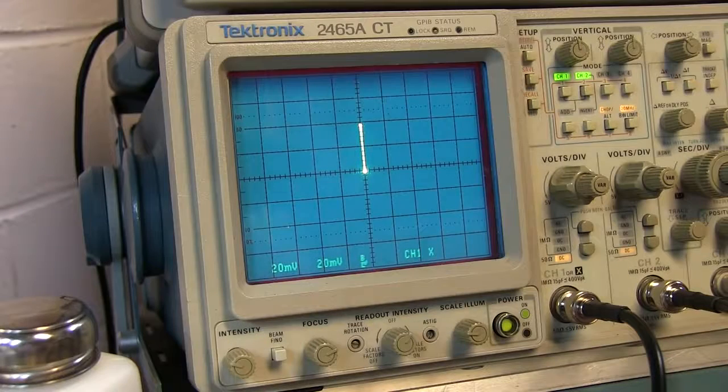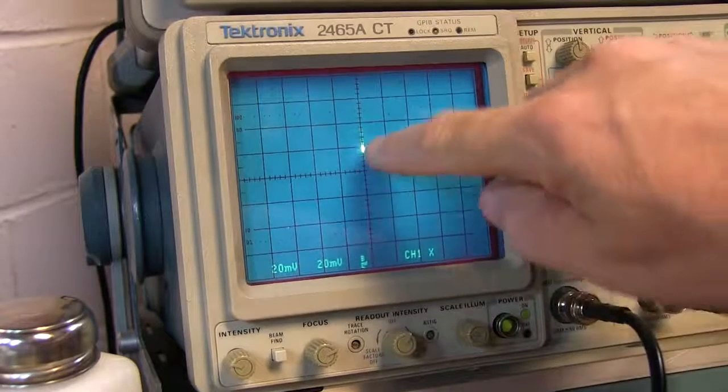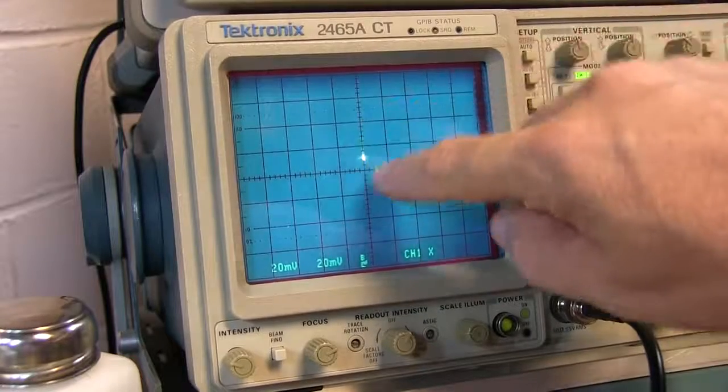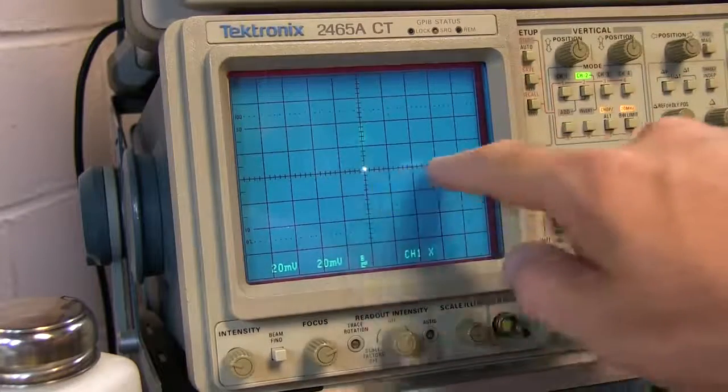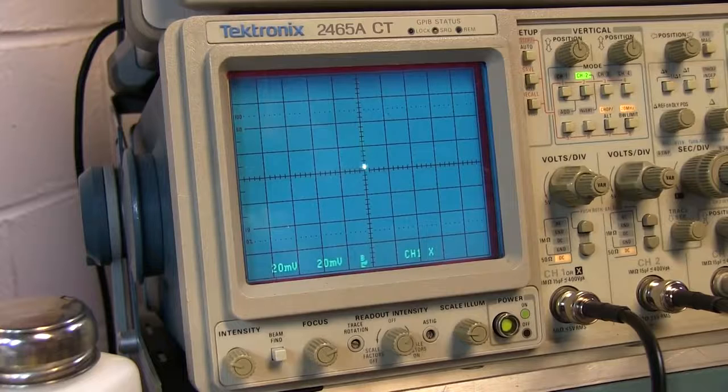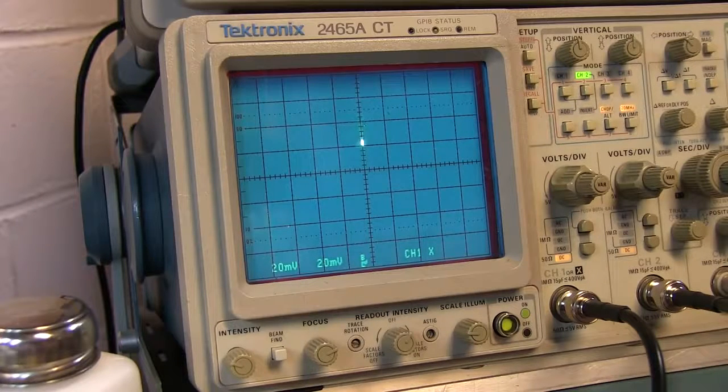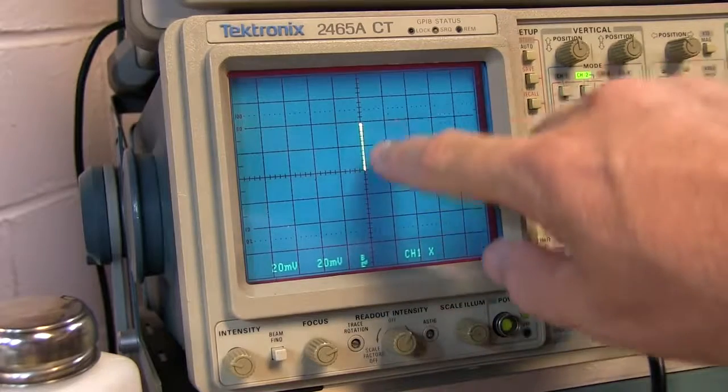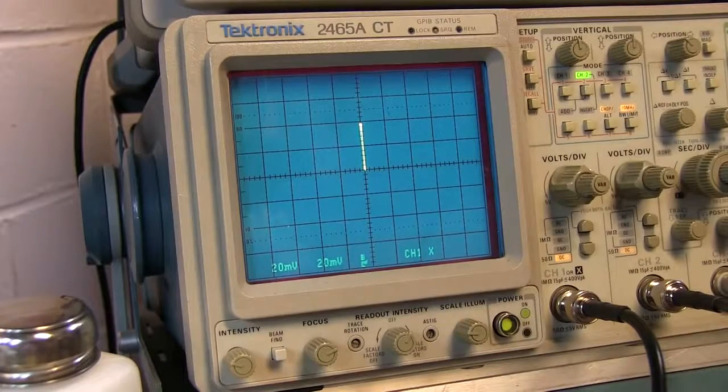If I slow the amplitude modulation baseband frequency down, let's bring it down to say 1 Hertz, now you can actually see the amplitude of just that Q component varying, with the I component being 0. Now for the purposes of visualizing that vector or that phasor, let's keep the baseband frequency up high enough so that it looks like a nice solid line. Now I can actually see what's going on.